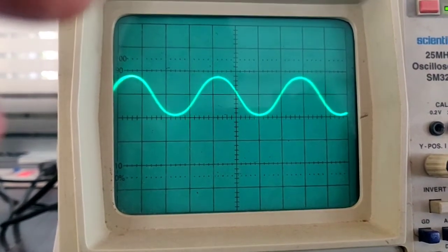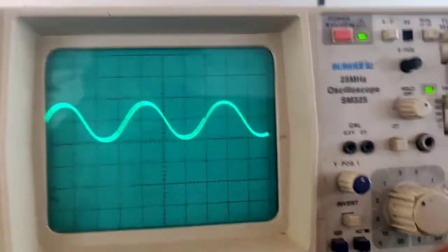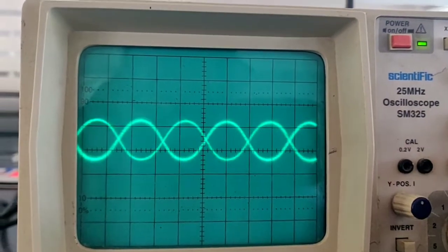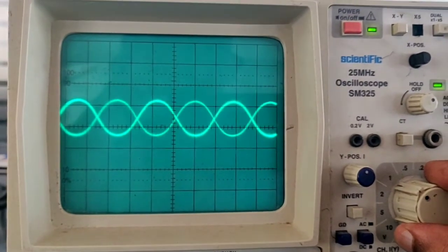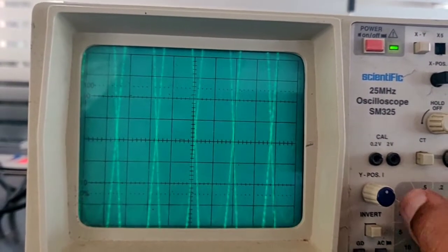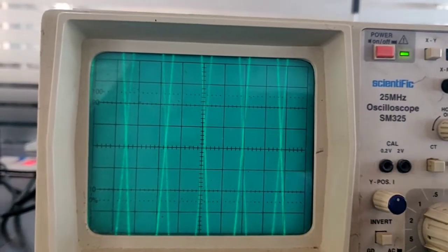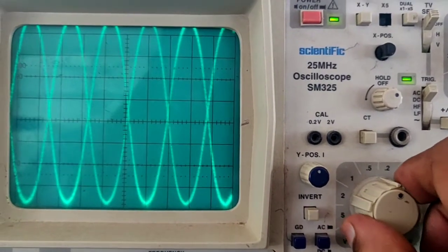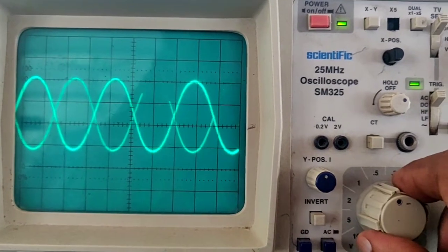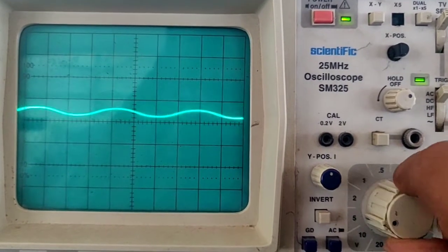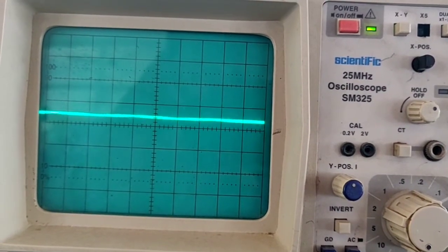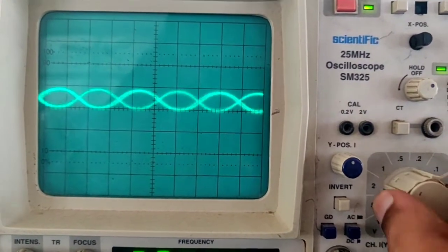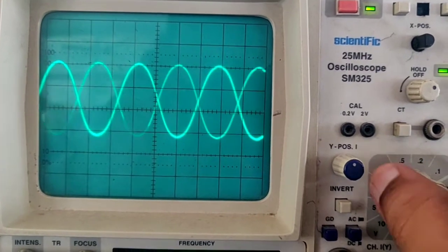What I have to do here is first get the trace by adjusting. If the trace is somewhere here, get it down. The first work is to adjust the volts per division control like this. Do not go for this, that is not a suitable scale, and change it to this. Okay, I am not satisfied with this because I am not able to take the reading. This is okay. At the same time, do not select the least range. I am not able to measure this. I think students also understand this. So select a suitable scale. This is okay. This is also okay.